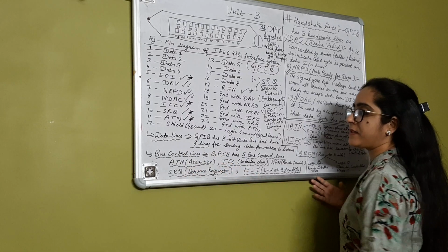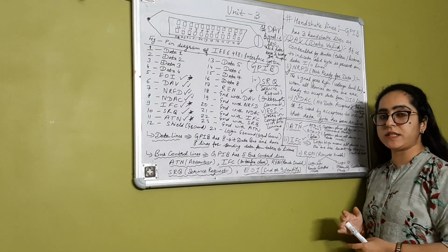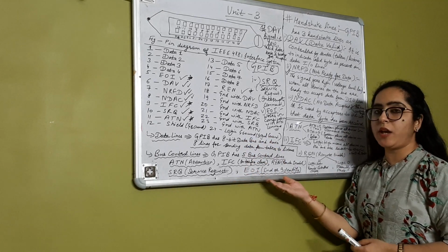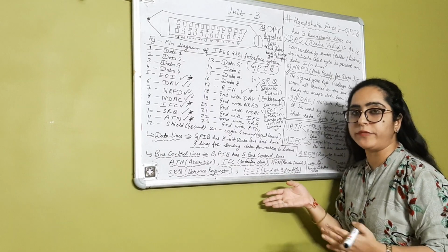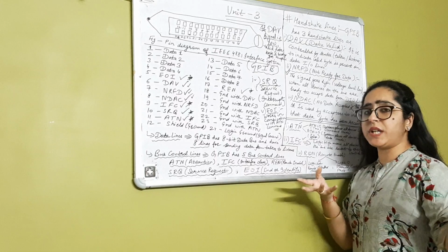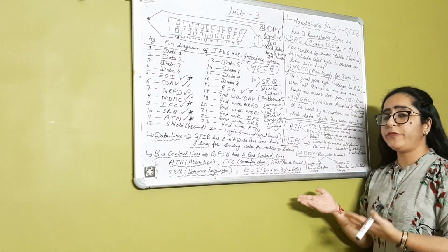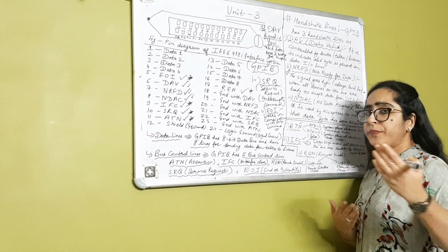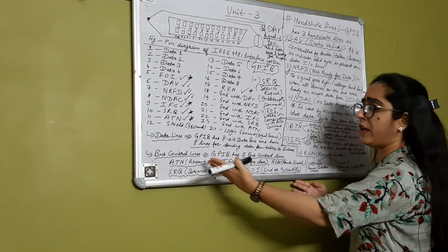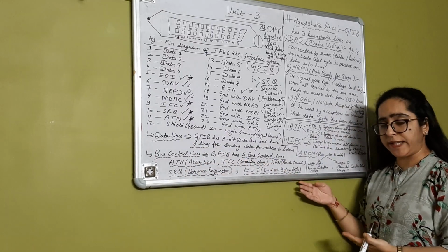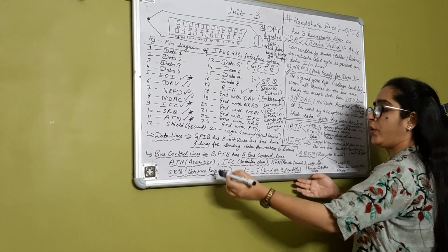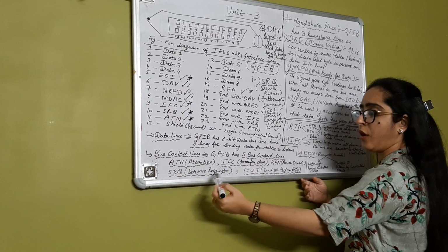Now next are our bus control lines. Bus control lines are needed in the system for controlling the operation of the system, or the flow of data management, from the controller to the listeners or from any other talker device to the controller. This operation is controlled with the help of 5 control lines, of which 4 are operated by the controller.